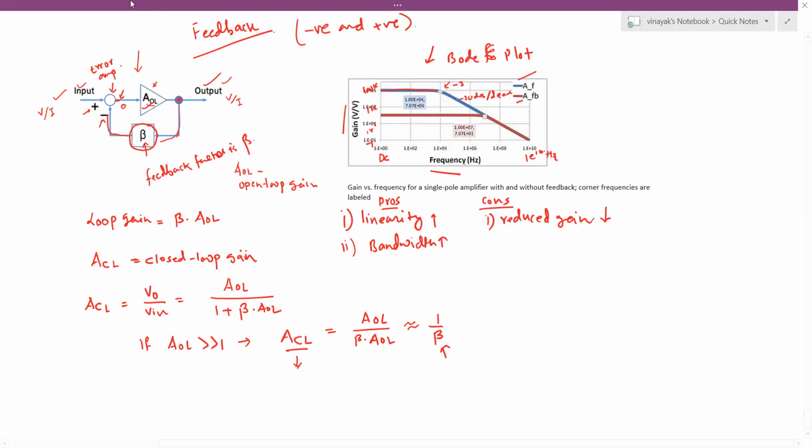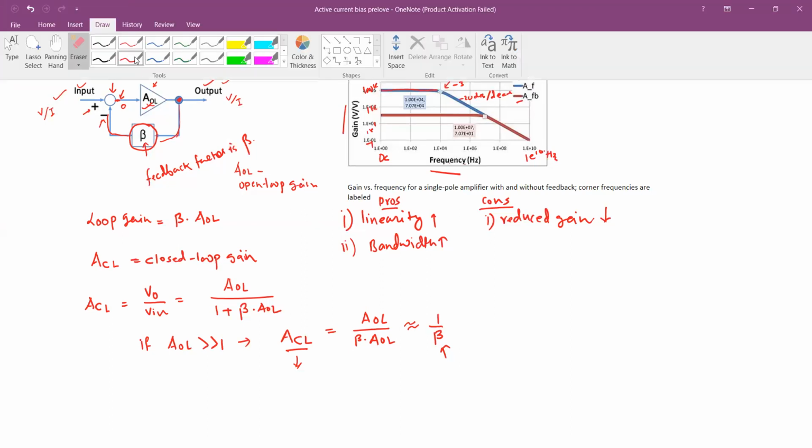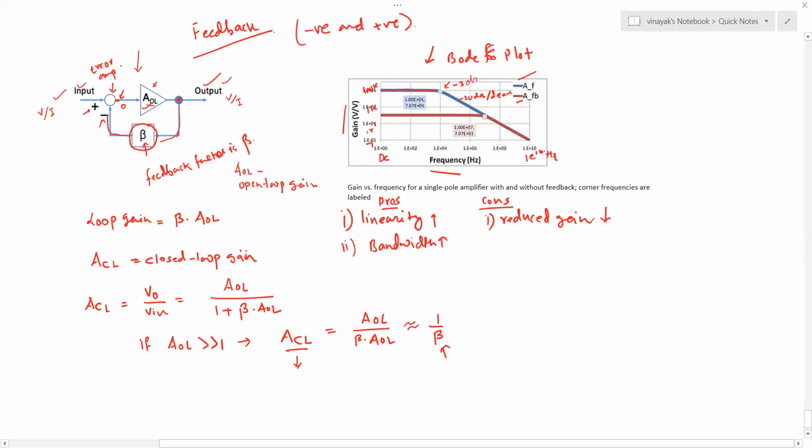Yeah, so here is my 3 dB point, and this is the slope where I see that there is a drop of the signal at the rate of -20 dB per decade. Okay, and then I have a constant gain as shown here up to the frequency 1 times 10 to the power 4. So that is 10 kilohertz.